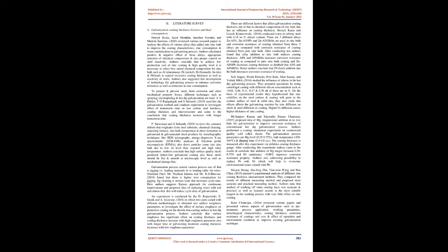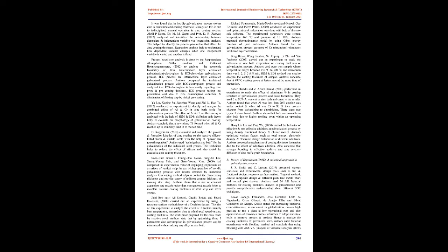On the basis of experimental results, they hypothesized that zinc solidifies on the steel surface and the coating will grow in the contact surface of steel and solid zinc. They also claim that silicon affects the galvanizing reaction by zinc diffusion on steels and steel diffusion on the coating. Higher Fe diffusion causes higher thickness of zinc coating.